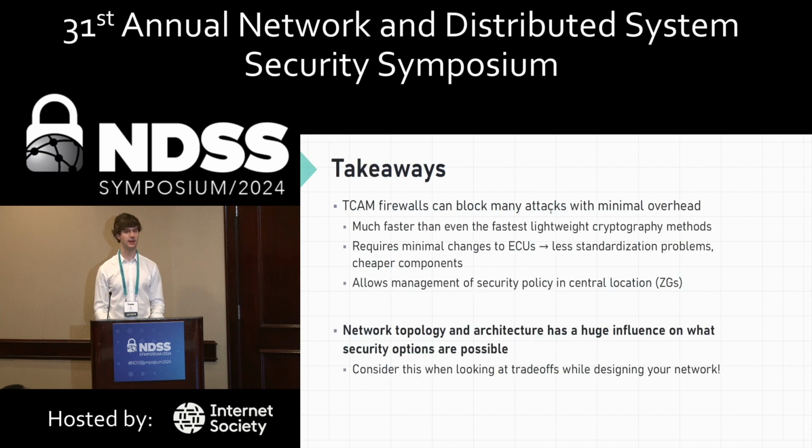But the big takeaways that I want to convey are this. TCAM firewalls can block many attacks with very little overhead if you can manage it. And they're much faster than even the most lightweight cryptography methods out there. They require almost no changes to your ECUs, which makes it way easier to get components from suppliers and cheaper. And they also let you manage your security policy in one single place, the gateways.